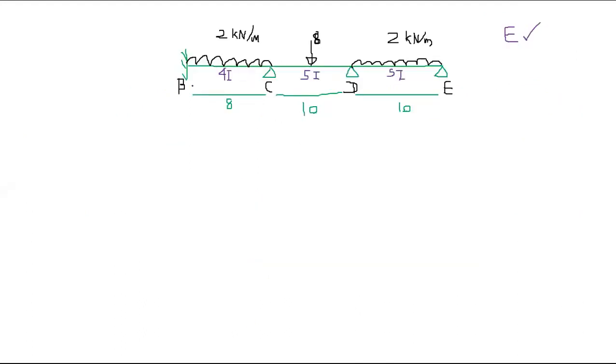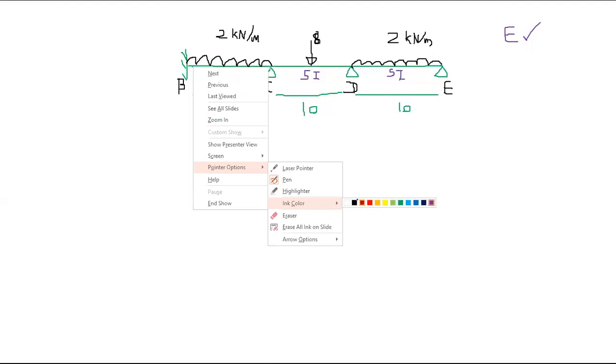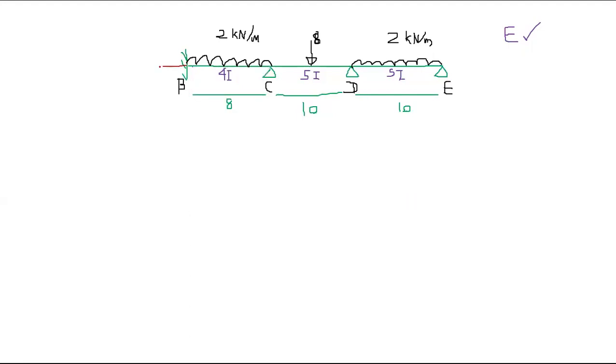So what you need to do first is to extend this one, to take the mirror image. Exactly, this is A. So 8 meters, you don't need the loading. What you need to do is EI, you don't know the I value. You don't need to worry on the I because EI for this part is infinity,